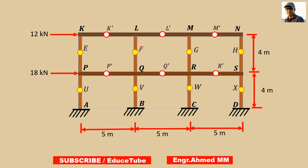But here all the columns we are considering have equal cross-sectional area. So the axial forces in a column are proportional to its distance from the centroid of the column areas.